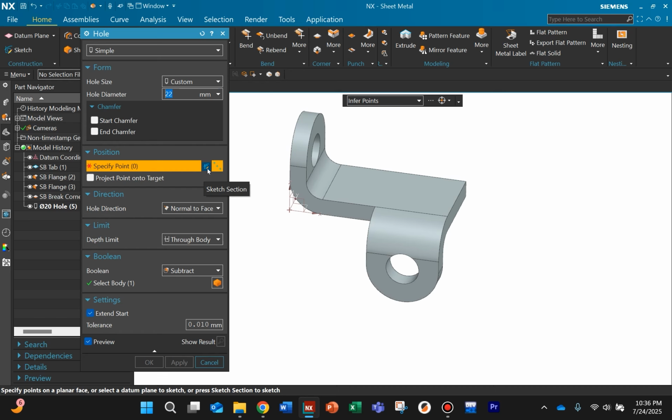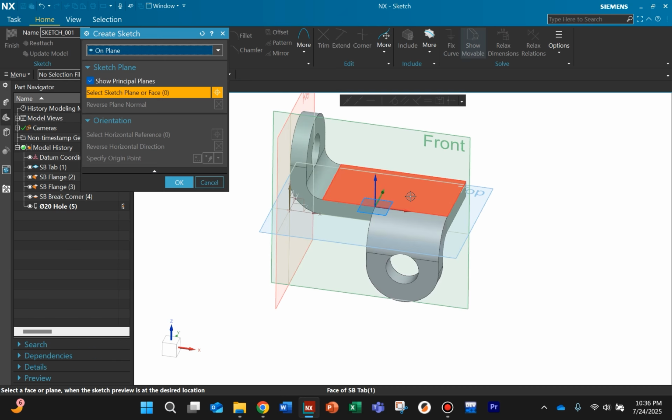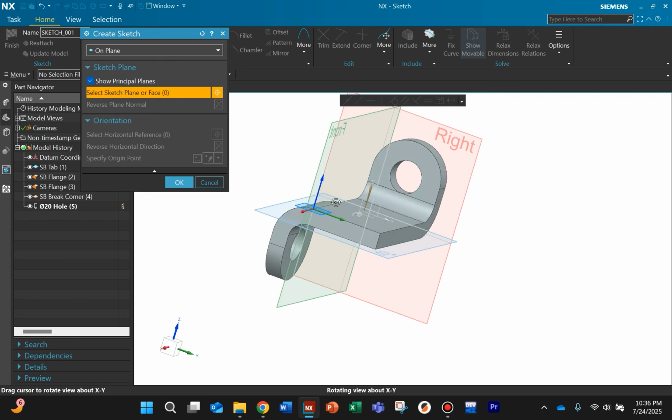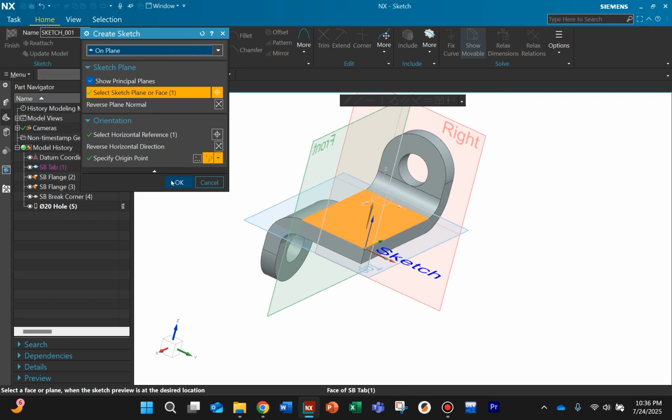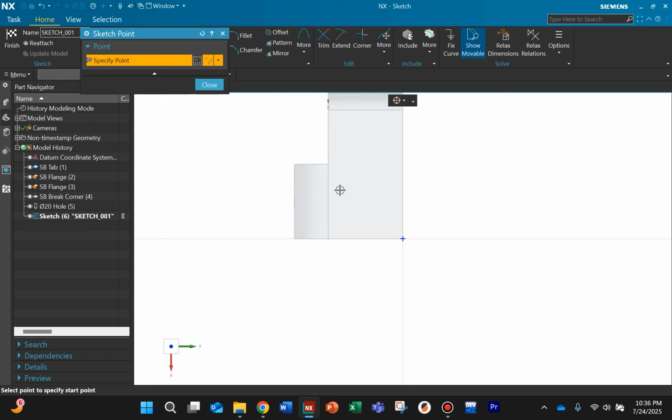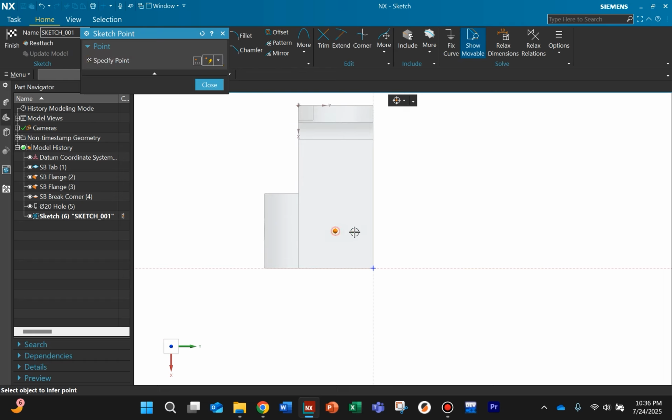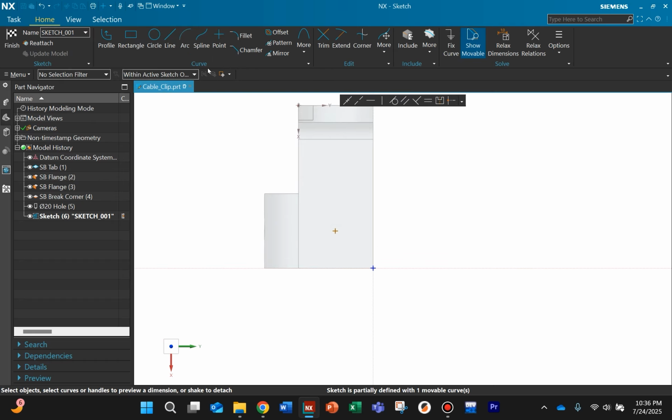And we are going to go to the sketch section to create the center point for this hole. This is going to be on this top surface of our part. I'll just place the point down kind of close to where it needs to be, and we're going to use our constraints to align this with our 2 flanges.